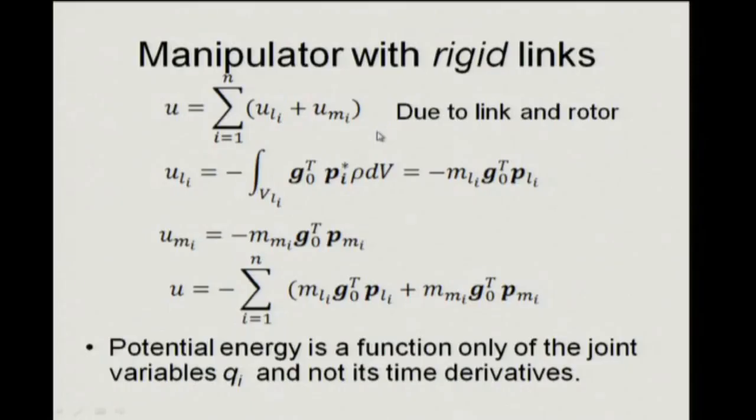Typically you reduce because you want to increase the torque, and motors are fast enough, especially electrical motors. Speed is not a problem, torque is a problem. So there is a step down drive, 100:1, 50:1 is the typical ratio that you are interested in. In rare cases you go in for an epicyclic drive, which is a much higher ratio. So it needs to be handled separately.